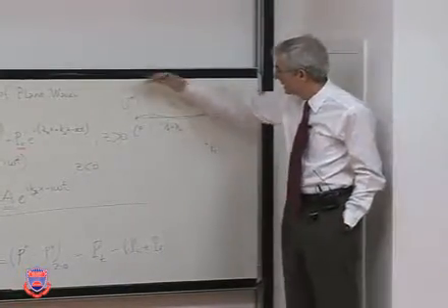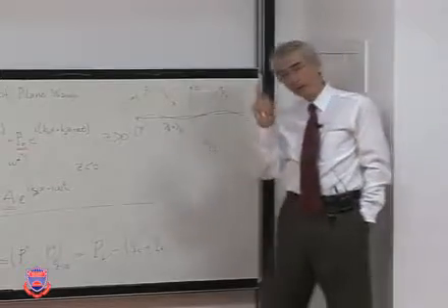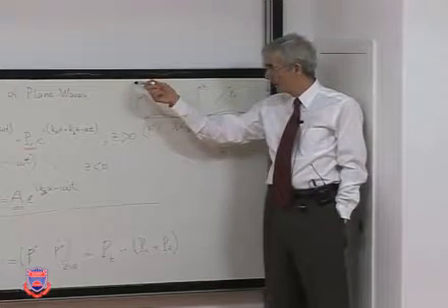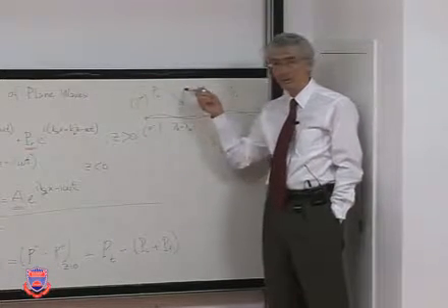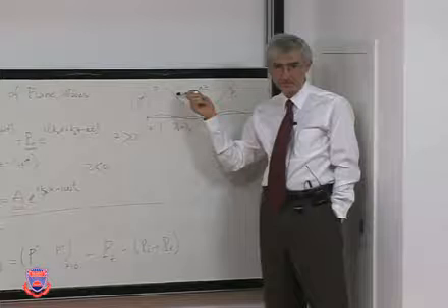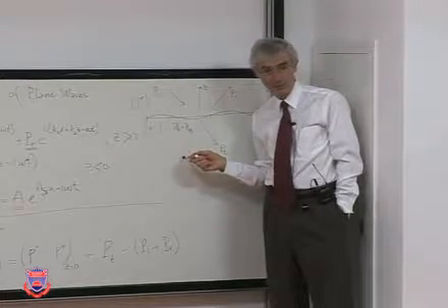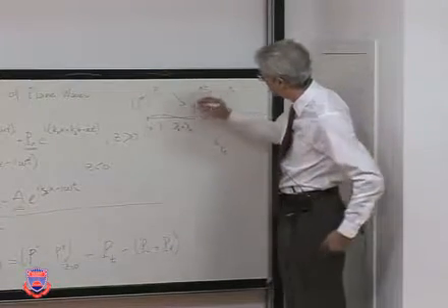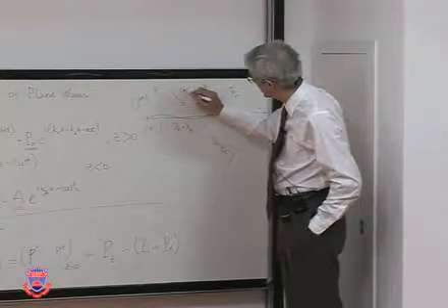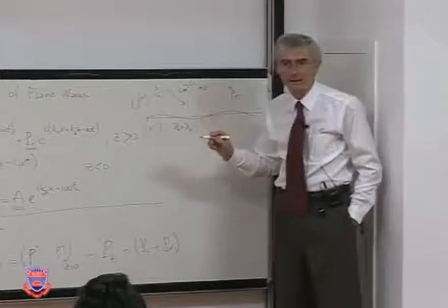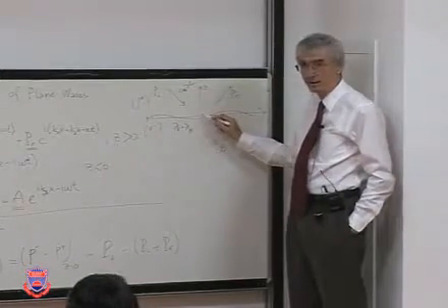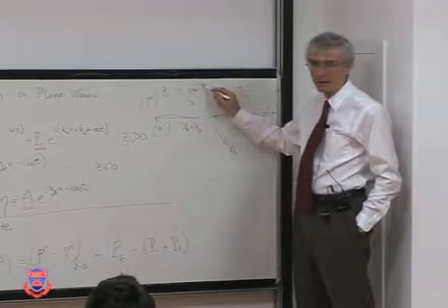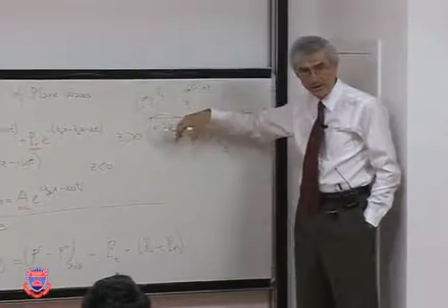Here's something else though. That is true with respect to this medium. But if you have a different medium on this side, that may not be true, because in effect, bending wave speed is always larger than the speed of sound, just the way it is being excited.